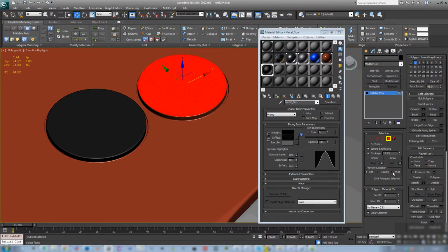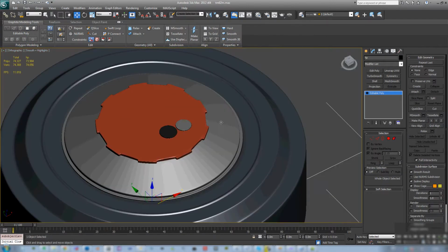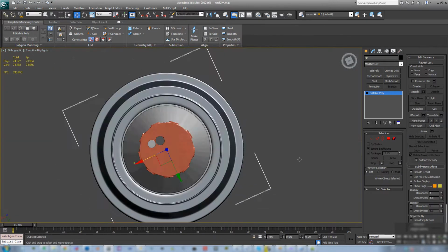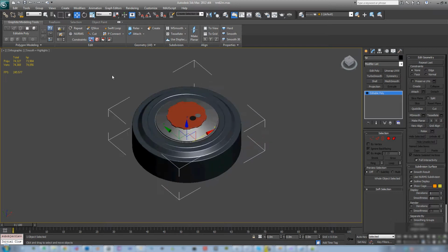Now this is important. This is why I don't just export the diffuse texture of the low poly, is because the low poly does not have this hovering geometry in it, and this is the information I really need to pass on. So I'm going to bake the high poly colors onto the low poly model. So the material assignment is complete at this point. I am ready to bake.